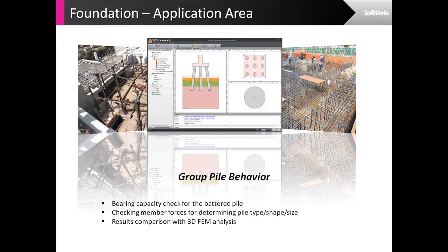This is a project application of the foundation module, in which you can see the group behavior in a set of arrangements that you created in the model. You can check the member forces, and that helps you to determine the different pile types, sizes, and shapes in order to have a better design.